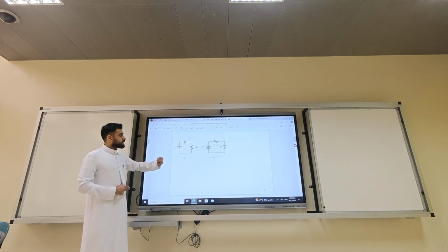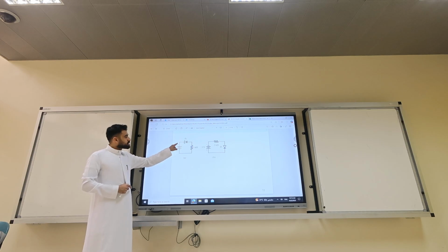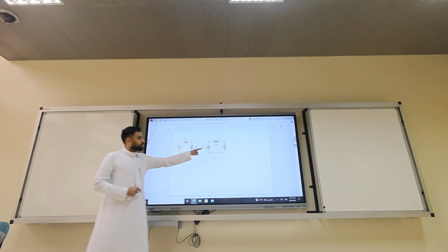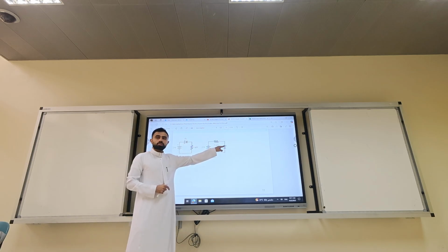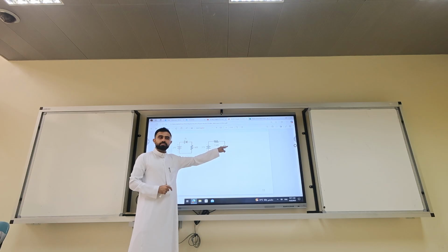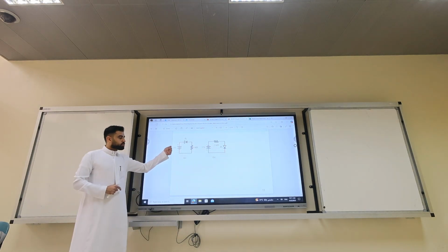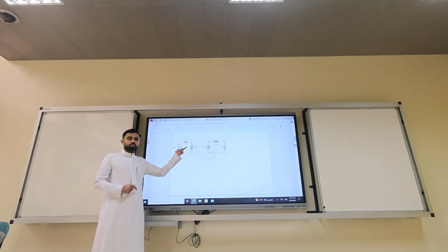We talked about this circuit. Remember this circuit? 2 is the higher voltage, so you replace it with a short circuit. Here -3 is closer to the anode. You replace it with what, Hatim? Open circuit. Awesome. When you replace this with a short circuit, how do you calculate the current? Ohm's law, 2/1, okay?